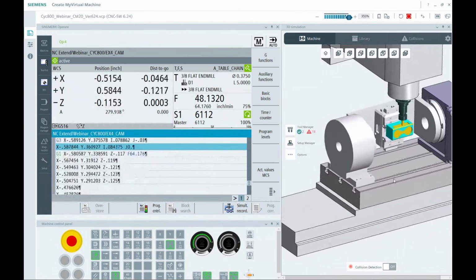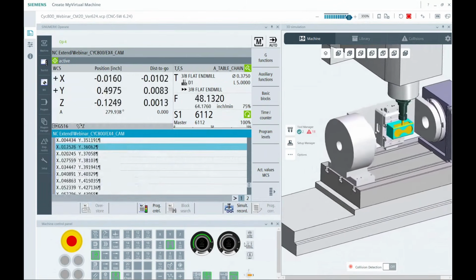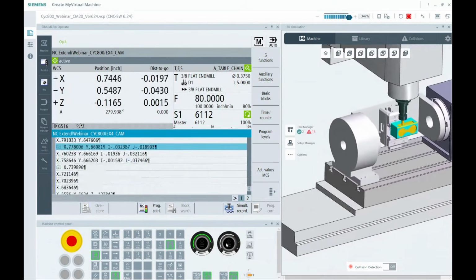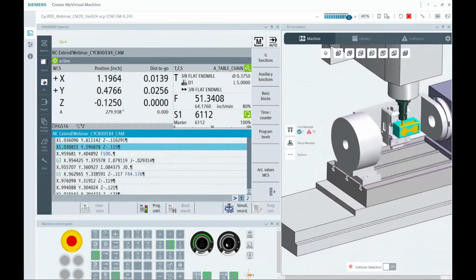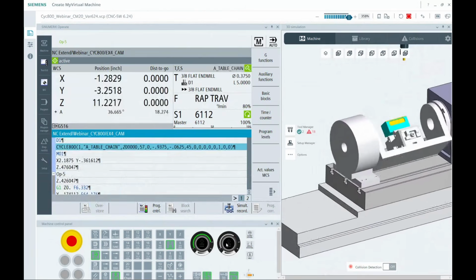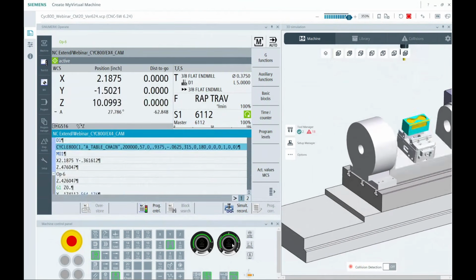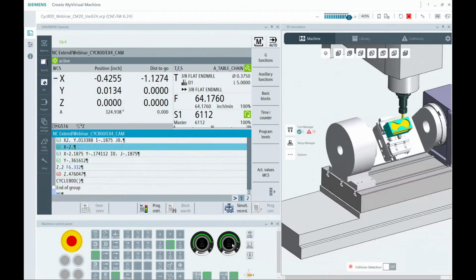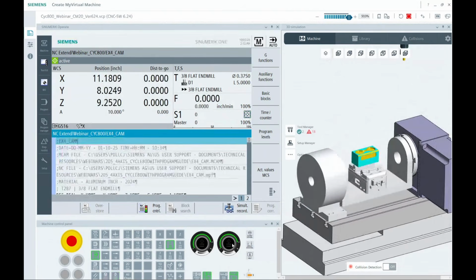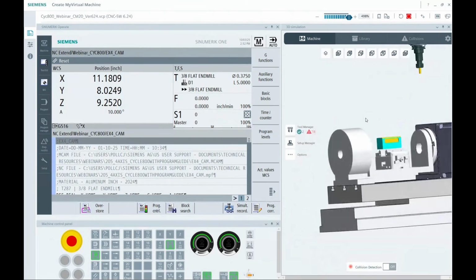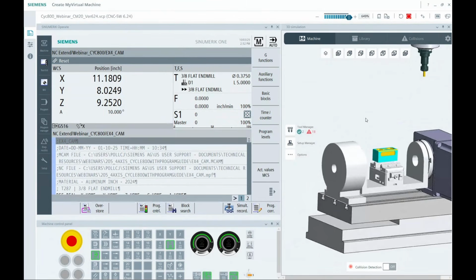So you do have to kind of play with that a little bit. If you are putting it in a scenario where it's got to do a 180-degree move, you may not have full control over which choice it's going to make. But then to finish it up, we'll do our 2 little chamfers. And then since I pushed the offset of my tilt into my little local variable there, I didn't do anything zeroing out the axis or anything, but it allows me to position it to 0.